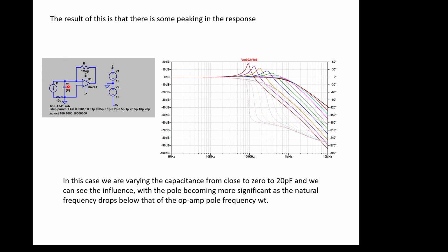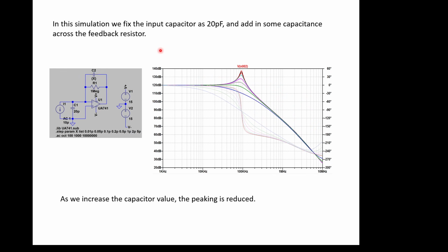Okay, so the ideal equations tell us it's all going to be wonderful, but with a little bit more thought, adding the capacitance in, looking at what the whole equation is and identifying it as a second order feature, we would expect some kind of second order response, and that's what we're seeing as we vary the capacitance. The question then becomes how do we calculate what the ideal capacitance is, and can we compensate for it? So we start to investigate that.